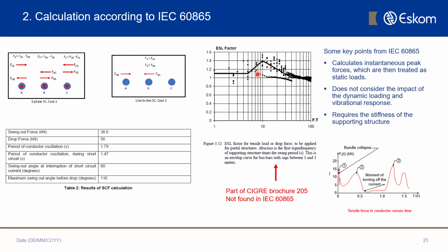It doesn't really conform to our characteristic load concept that we use as structural engineers. So even using this, you need to be careful. Another thing is that this particular curve takes the first vibrational mode shape only, right? Obviously you could have more than one vibrational mode shape that is important, but it still might be valid because it is a synthetic curve.